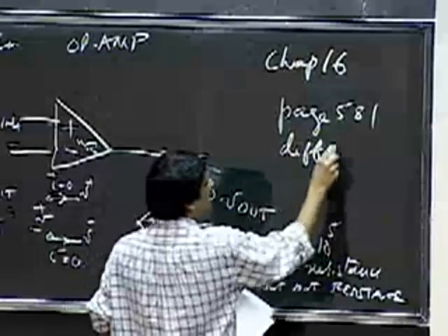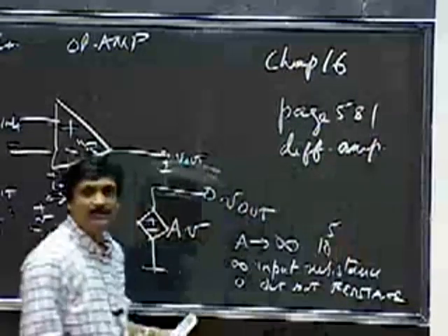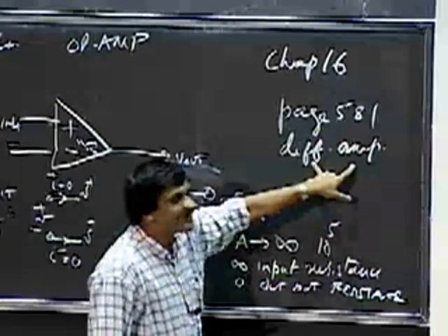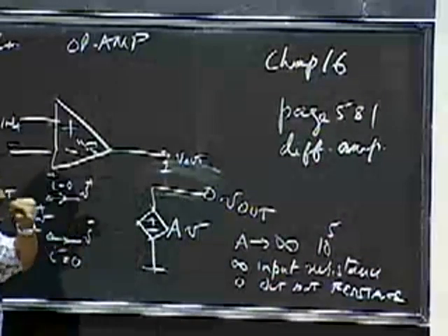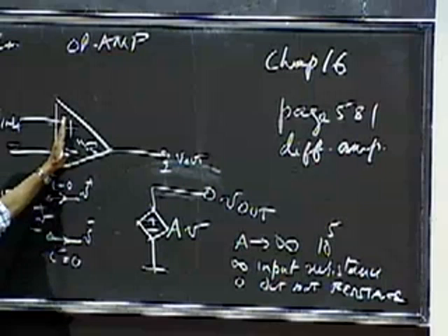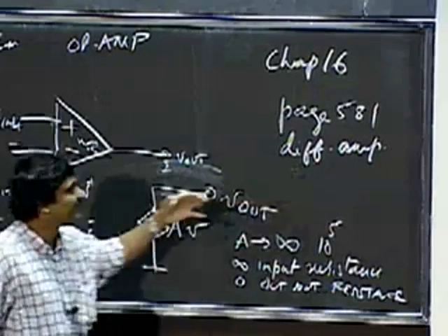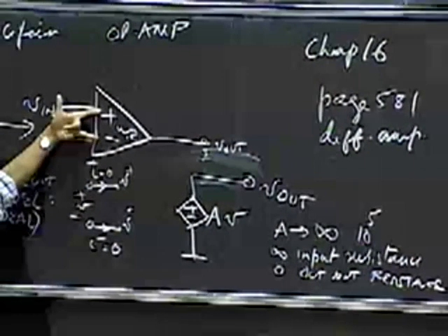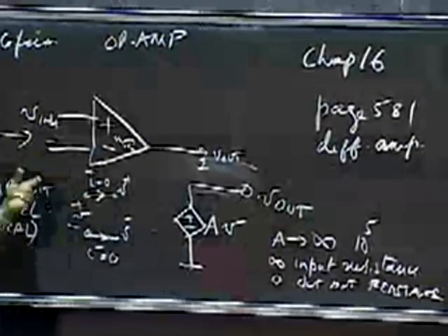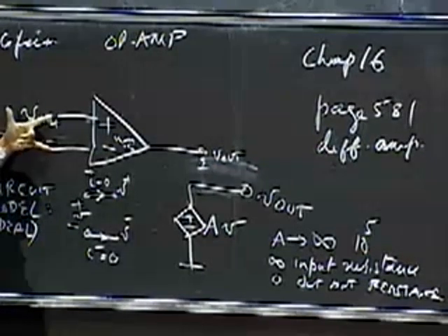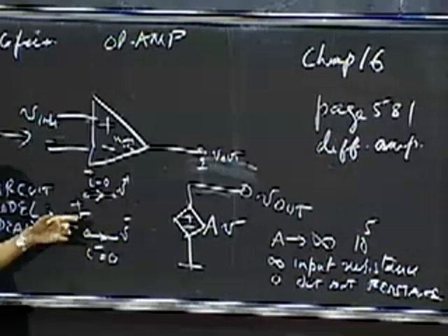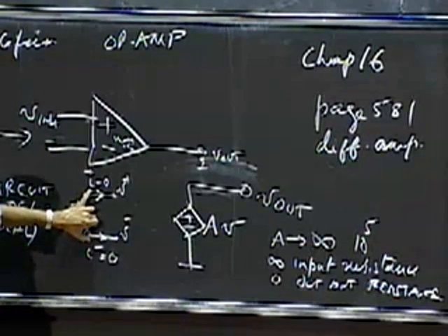for a differential amplifier. This is the small signal analysis chapter. That differential amplifier that's solved in that example is usually the first stage in an operational amplifier circuit. That differential amplifier is usually the first stage at the input. And that differential amplifier, as the name implies, amplifies not a single voltage, but a differential voltage. Note that this guy amplifies the voltage difference between these two terminals.